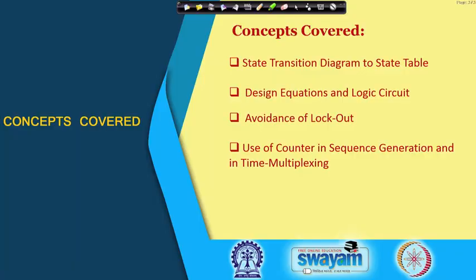clock cycle. So, in this particular class we shall see how a synchronous counter with different modulo numbers can be designed, and that design can be considered as a synthesis sequential logic circuit design problem. And we shall see that those kinds of glitch will not occur. It does not require going to the next state. Straight away the next valid state in the sequence as per the modulo number, if n unique states are there, those n unique states will appear one after another. And we shall also look at some specific applications other than the ones that we have seen before.